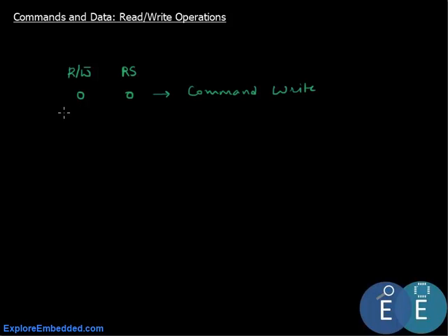When the register select is 1 and read write is still 0, the data register is selected. That means we are sending data from the microcontroller.